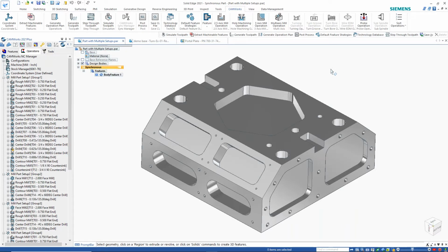So that quickly I'm able to machine parts and program parts. And keep in mind that if there are particular processes that I want to change over here, and we'll look at that shortly when we go to optimize a part of this program, we can make changes to it and then save it back to the technology database, and it will reproduce that automation just exactly the way that we decide we want it. So you can capture your best practices into the technology database.